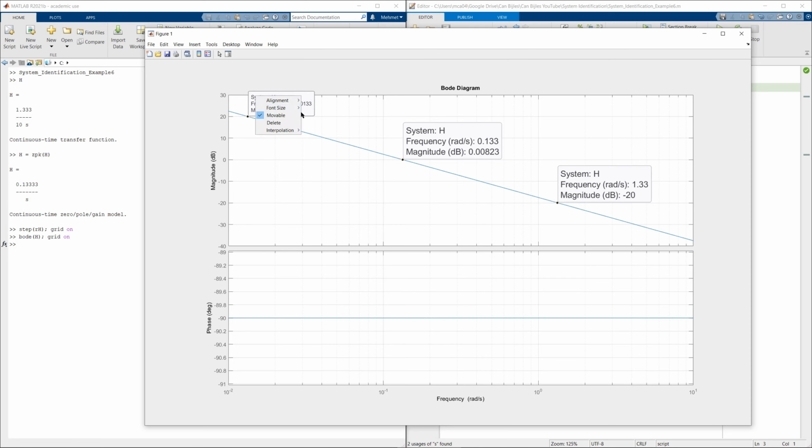And again, for completeness, if I make this 10 times smaller frequency, I will have this frequency, and you can see it is now plus 20. So I have 20 dB at this frequency. I increase the frequency 10 times, I get the dB of 0 approximately. And if I increase the frequency again 10 times, so one decade, I will again have a reduction of my gain of 20 dB. So you increase your frequency 10 times, you go down by 20 dB. And as you can see, the phase will always be minus 90 degrees. Doesn't matter which frequency you take, it is always minus 90 degrees.